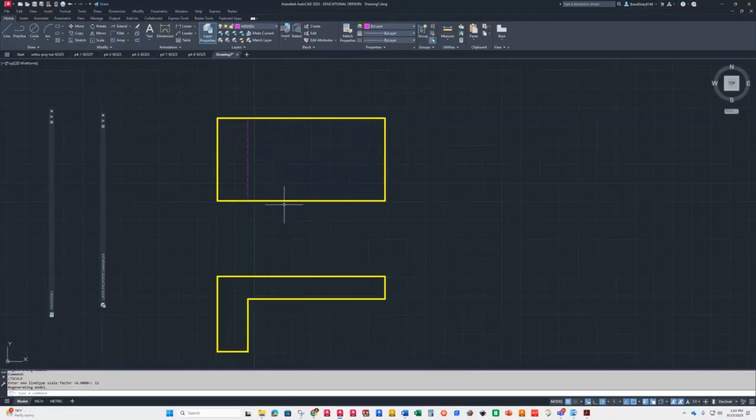The next thing that I could figure out is I've got this hole. It says it's 35 off of here. So let's offset over 35. Or, some of you guys might do it this way. It's in the middle. You could just draw you a line from the middle over 35. And that's where your circle is going to be, the center of it.